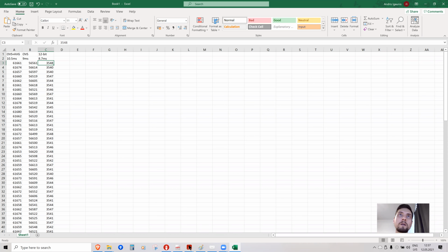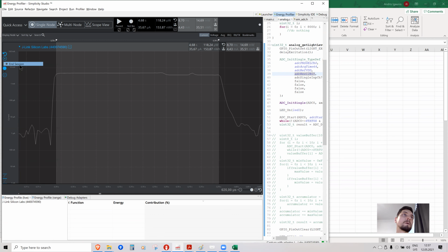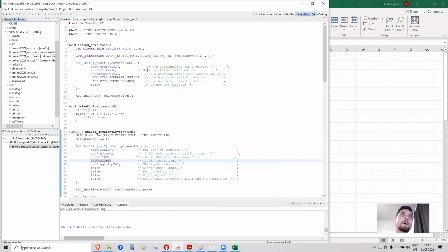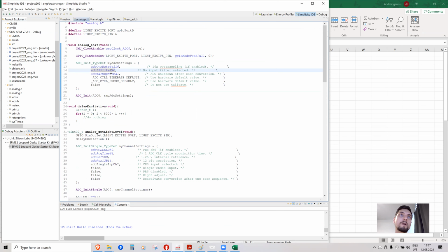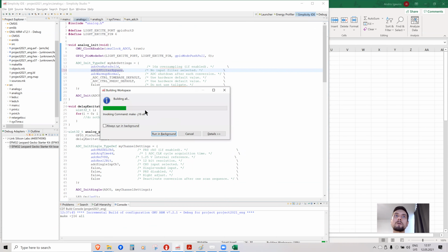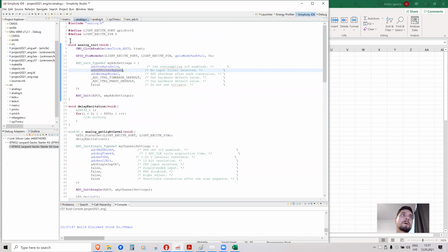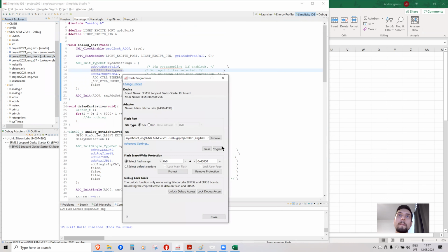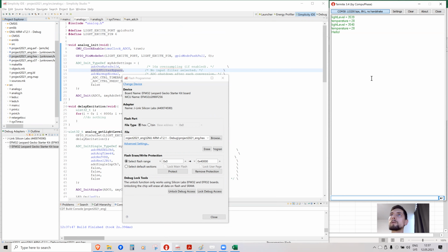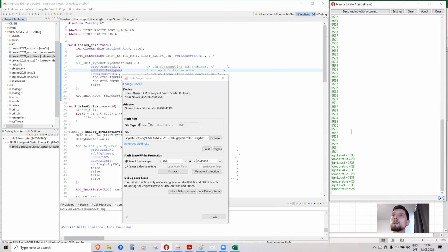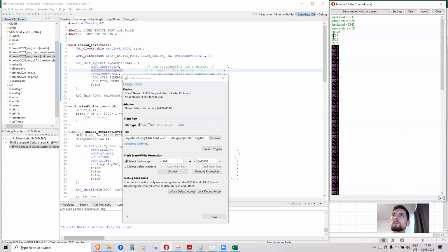And now, finally, let's also do the test with the RC filter off. So in the analog to digital converter settings, I will now switch off this RC filter, and it will be directly connected to the signal with no filtering, and program. And I expect that, of course, we will have even greater variability in the output. Okay, so let's pause this and put it here.